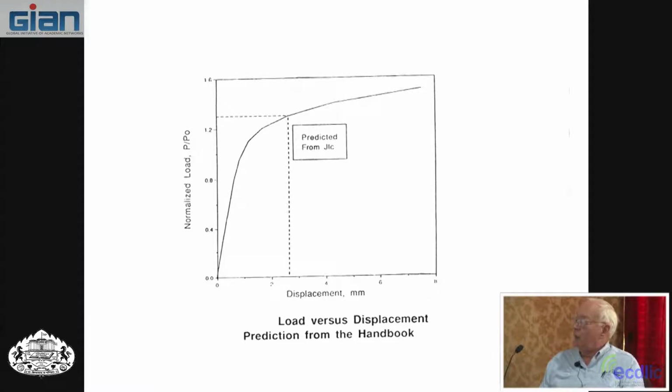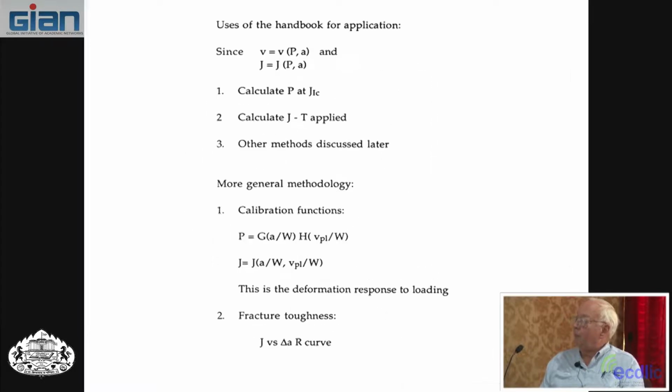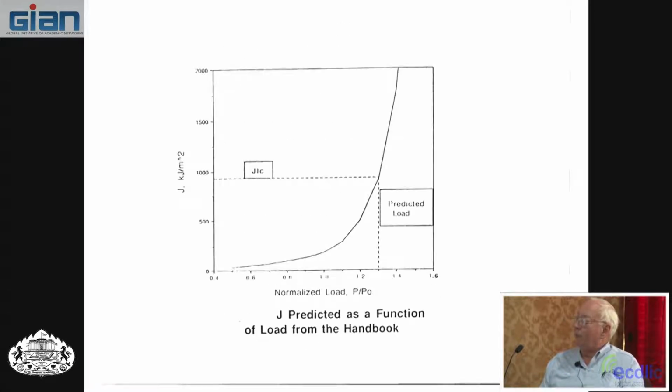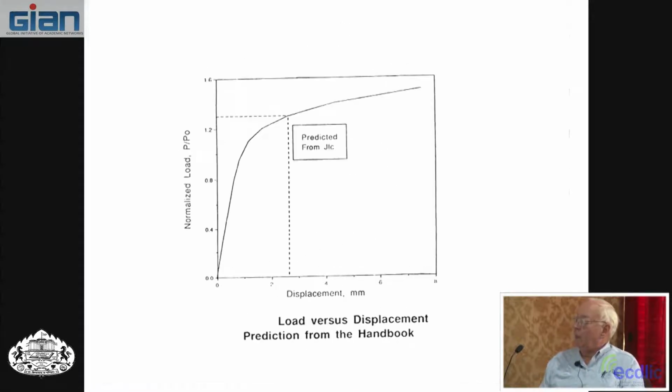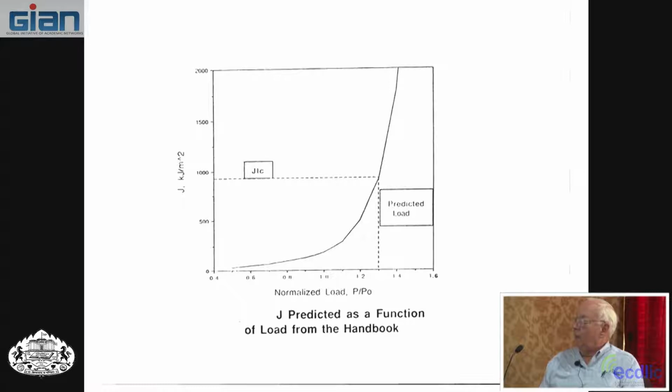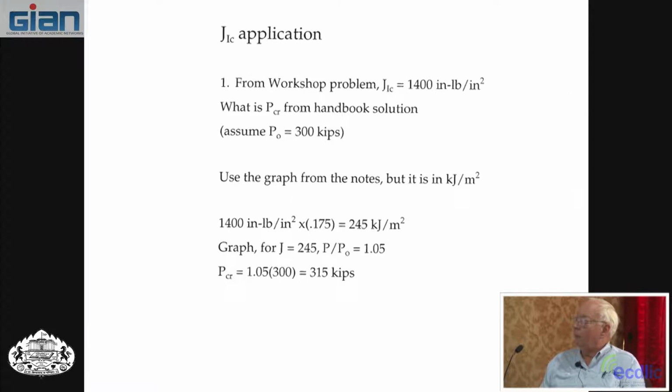Because you can predict displacement as well from this, load and displacement and J and crack length all go together, you can predict load versus displacement as well. These loads then would be for a given crack size. You would pick the crack size to start with.